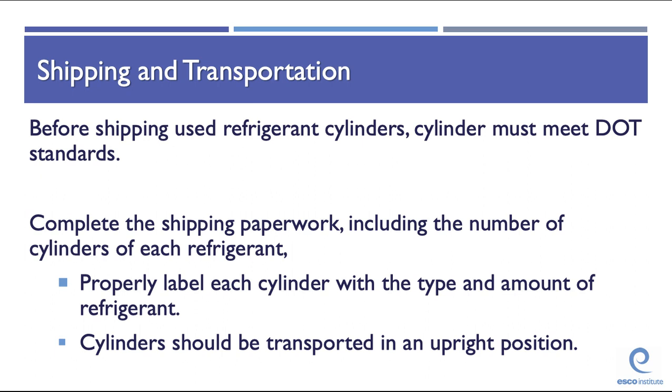Before shipping any used refrigerant cylinders, check that the cylinder meets DOT standards. Complete the shipping paperwork, including the number of cylinders of each refrigerant, and properly label the cylinder with the type and amount of refrigerant before returning for reclaiming. Cylinders should always be transported in an upright condition. Once it is shipped, it is regulated by Department of Transportation standards.